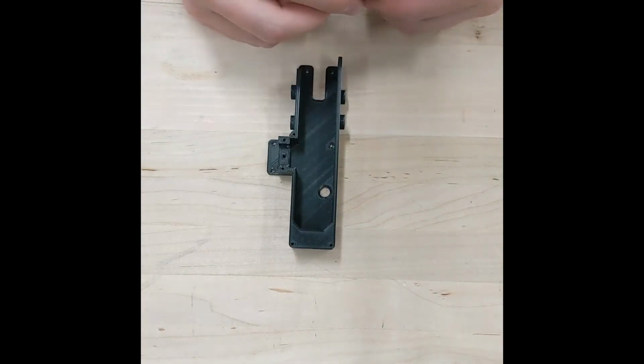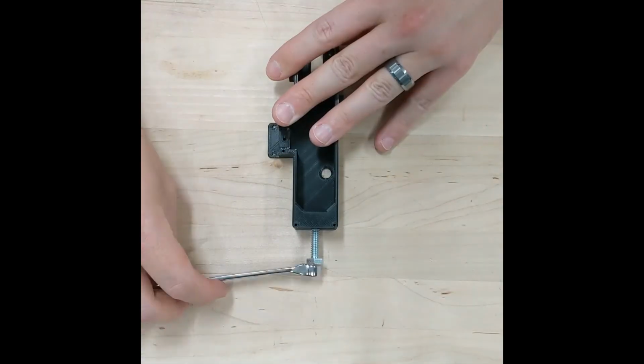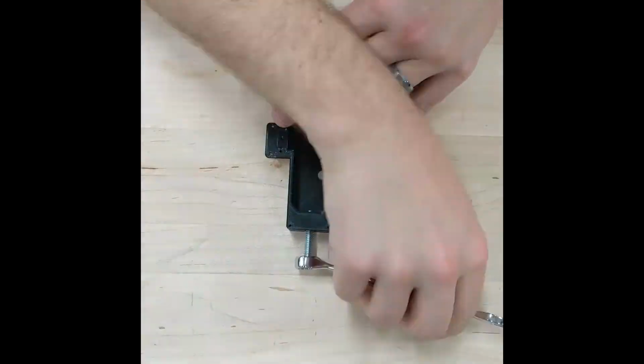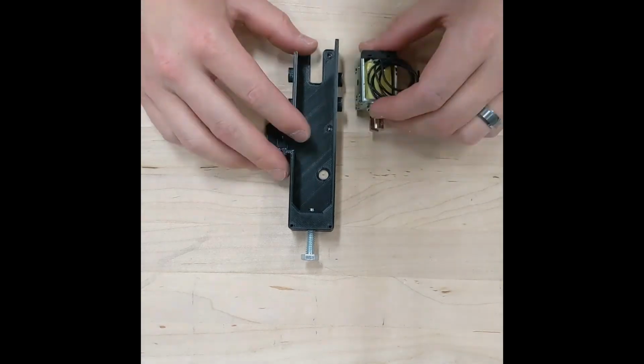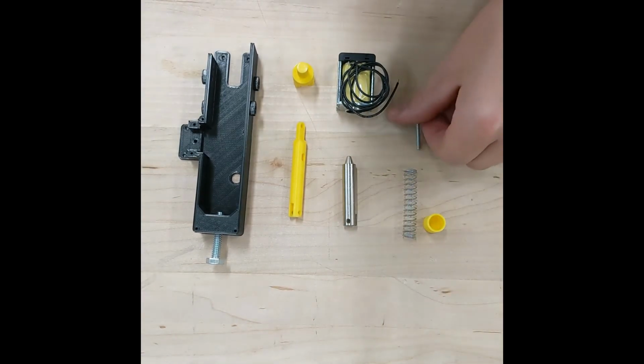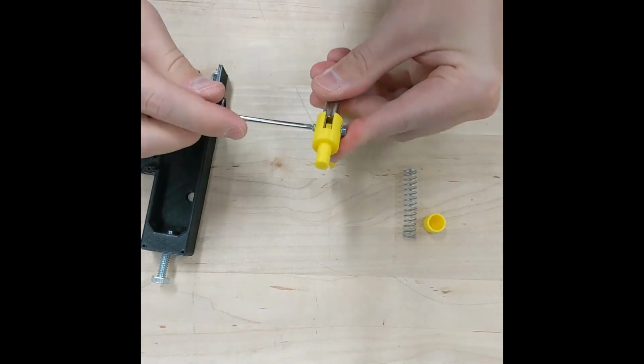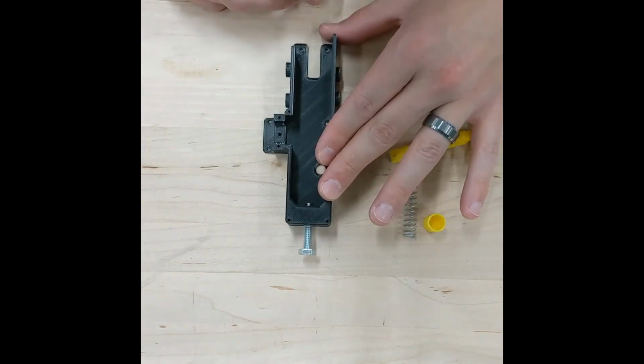In the original design, the solenoid in the locking mechanism was supposed to be a push solenoid. This would allow the solenoid to push the locking mechanism up to unlock the locker and then lock again once power was removed from the solenoid. However, due to supply limitations, there was not enough time to have push solenoids delivered, so the design was altered to utilize a pulling solenoid instead.